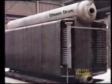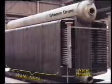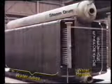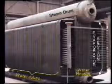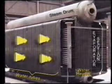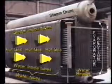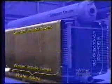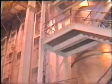First, let's see how steam is formed in the water tubes of the HRSG. This steam-generating zone is often referred to as the evaporator section, as this is precisely what happens. Heat is transferred through the tube walls, and the water is evaporated into steam. In order to promote natural circulation, the boiler tubes are arranged vertically with the hot gas passing across the tubes in the horizontal direction. The exit gas is directed into the bottom of the stack.